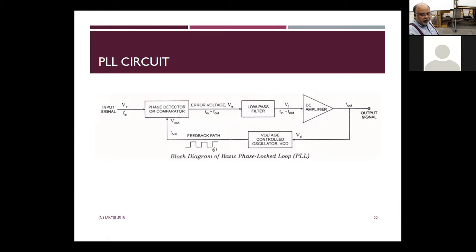The VCO adjusts its voltage so that the output oscillations become both in phase. They cannot be in phase unless they are at the same frequency, so in-phasing includes frequency also. Right before you start, there is some time before the voltage-controlled oscillator catches the input clock.